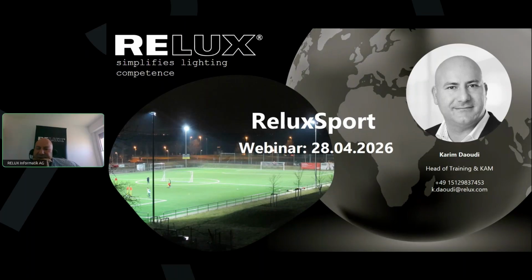I have shown you how to do that. There are different ways to do that. The best way is to go to the luminaire list and change it by hand. If you don't want to do it for each cell, then you have to go in the project tree to the poles, select them, and within the pole you can see how many luminaires you have on one pole. In the properties you can change this in one go. That's possible.